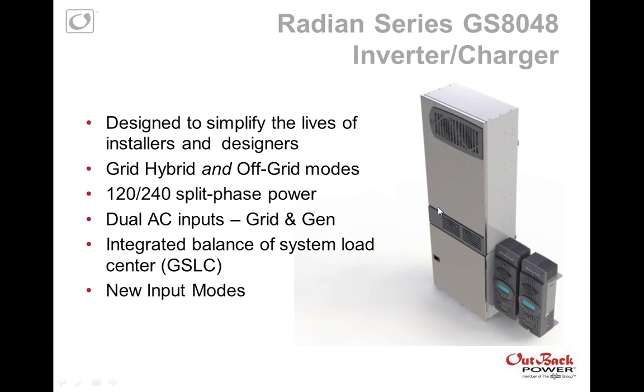Other than you do have to pass a wire bundle up into the inverter here with some quick connects. You don't even need a screwdriver. They just go right in and you have to hit the quick connect to tie them down. So it's all designed for a fairly quick and easy field installation because time is money in the field. And you can also get versions that are pre-wired for up to 2 charge controllers to simplify that installation as well.